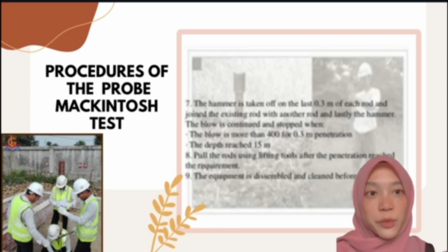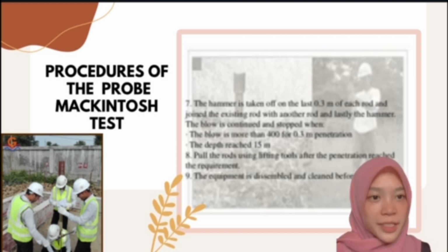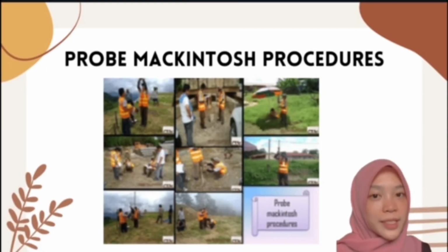Afterwards, record the weight of the empty dish. Then record the soil sample in the same dish. Additionally, place the dish in the oven to dry out moisture in the soil for 24 hours. Lastly, take out the soil sample and all data will be recorded in the sheet.